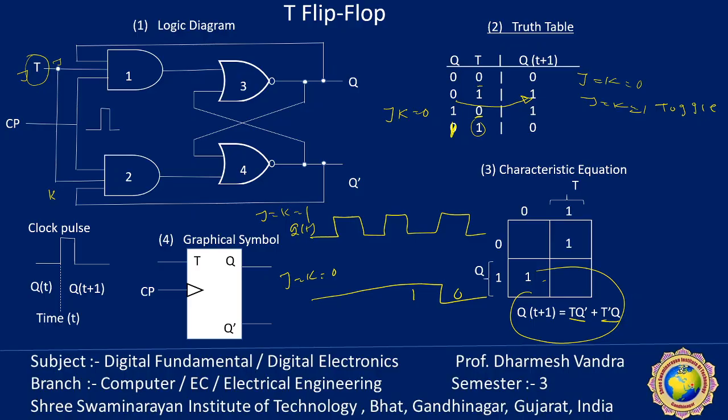Here in this flip-flop, the limitation is that the width of the clock pulse must be less than the propagation delay, or it must be an edge-triggered flip-flop, which we discussed along with the different types of clock pulse applicable for any circuit. So I hope it makes sense.